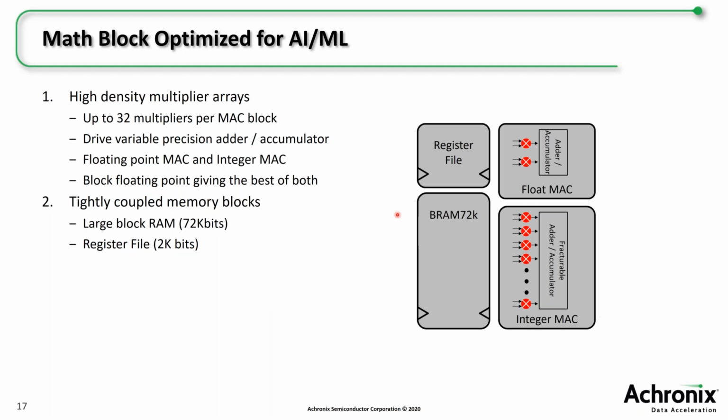So it's actually configured as a separate column that's adjacent to the multiply accumulate function, and so therefore it's addressable and you can route to it completely independently. But if you want to drive the adjacent multiply accumulate from that associated memory, there's a direct connection between the two. Direct connection means you've got a higher bandwidth. The direct connection means you're not using any FPGA routing. It's going to be easier to close timing, so it becomes much more efficient.